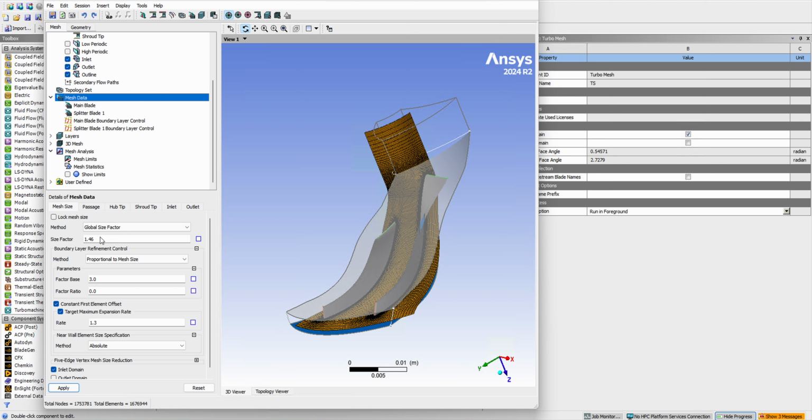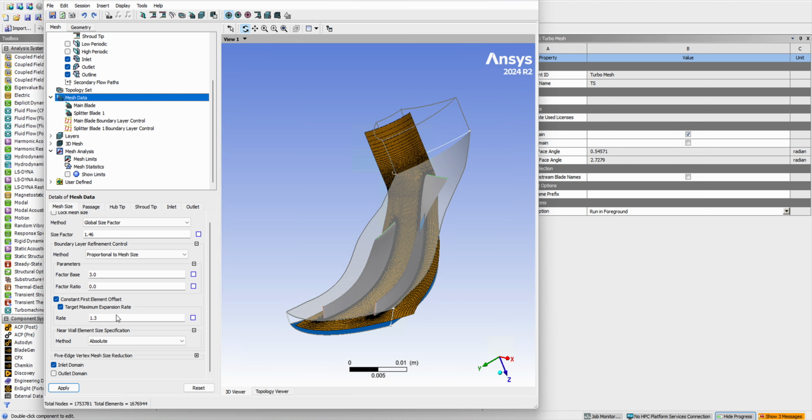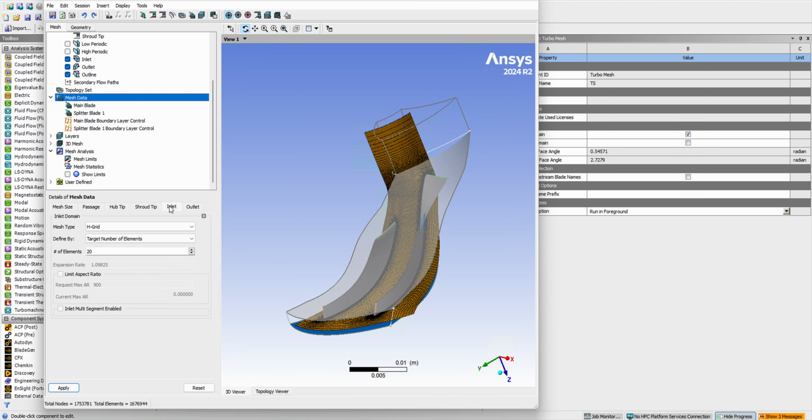Normally that helps. However, you don't want to increase this factor too much. It will make the boundary layer control unhappy. I'm guessing it's some sort of numerical or connectivity issue. There are these kinds of factors you can play with.